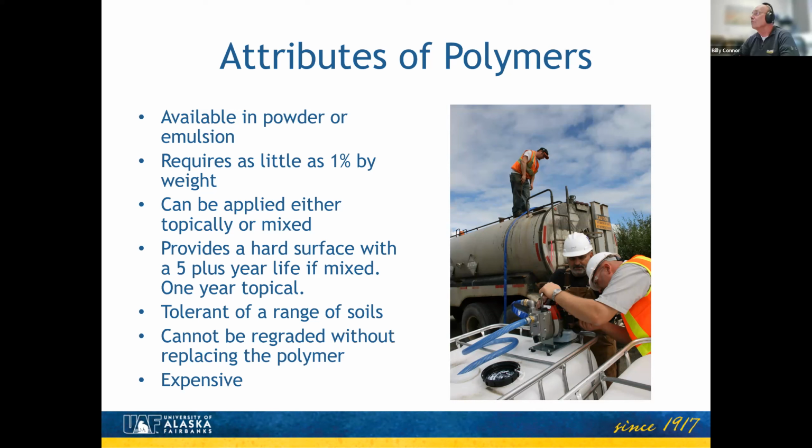We did St. Michael's using a D1 type material or base course type material and 1% by weight of the polymer. And as far as I know, it's worked pretty well. It's in its 2nd year, so we'll be checking on that this fall and see how well it's doing. It can be applied again, either topically, which is probably only going to get you about a year, or you can mix it in, and then you can get multiple years out of it. As I said, in Horseshoe Lake, we got 5+ years in that mix. So we had some pretty good luck with that.